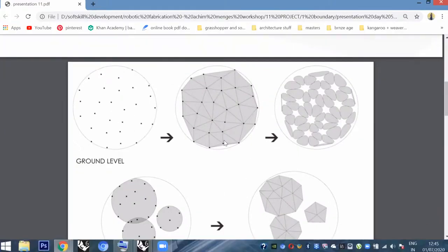And one thing that we had faced was when we try to stack vertically, we cannot go for a conventional packed stacking. Since the slabs are angular, we cannot continue the same way. The roof slab of the ground level could not become the floor slab for the first level. Was I clear? I think I confused a little bit.